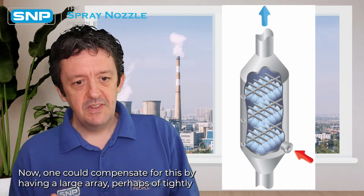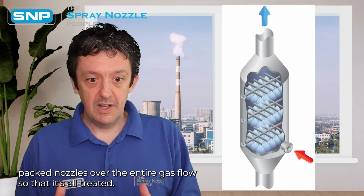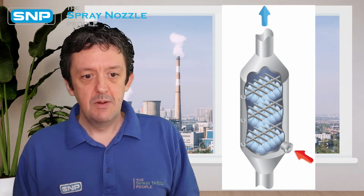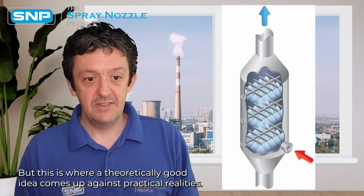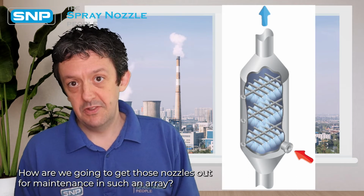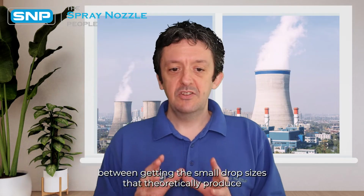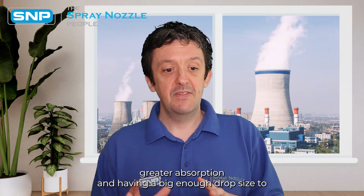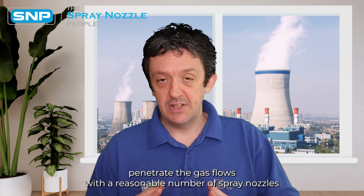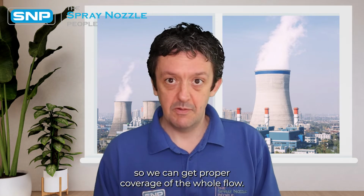Now, one could compensate for this by having a large array, perhaps of tightly packed nozzles over the entire gas flow so that it's all treated. But this is where a theoretically good idea comes up against practical reality. How are we going to get those nozzles out for maintenance in such an array? What about the cost of the extra pipe work, etc.? So there needs to be a balance between getting the small drop sizes that theoretically will produce greater absorption and having a big enough drop size to penetrate the gas flows with a reasonable number of spray nozzles so we can get proper coverage of the whole flow.